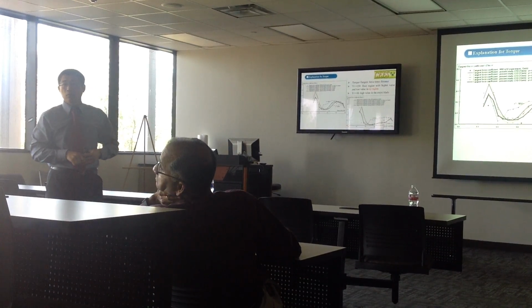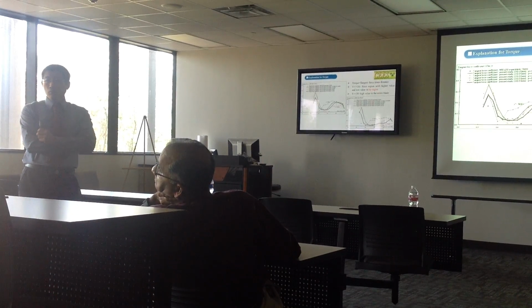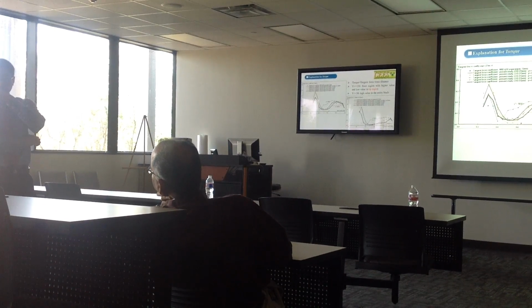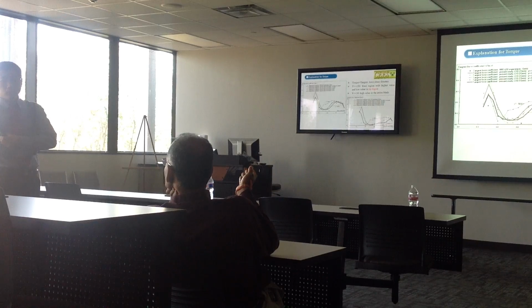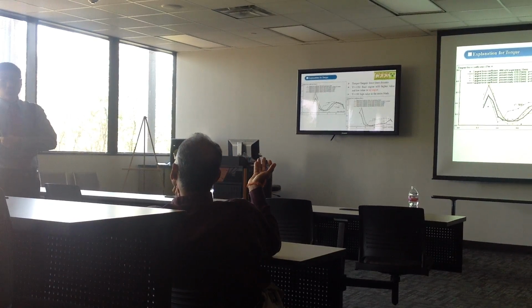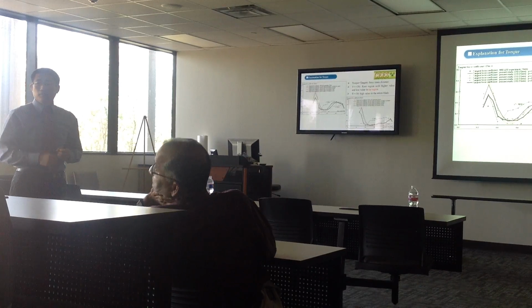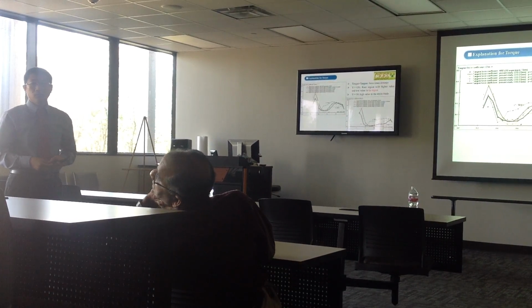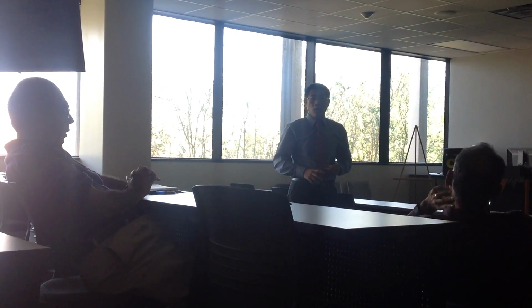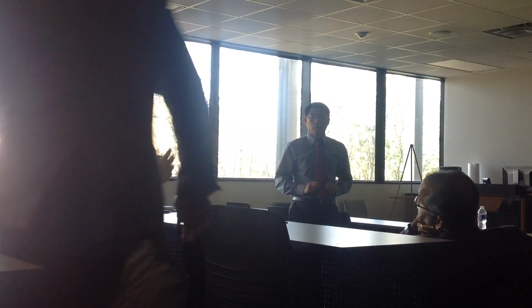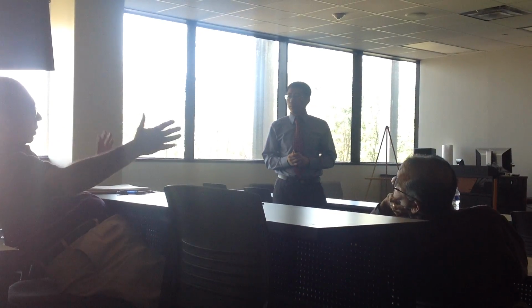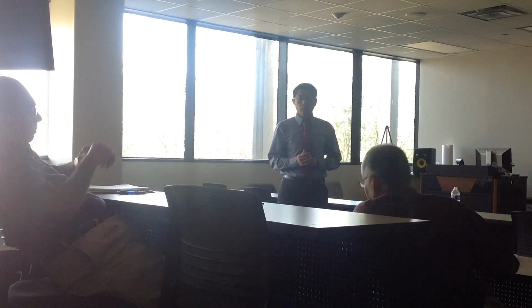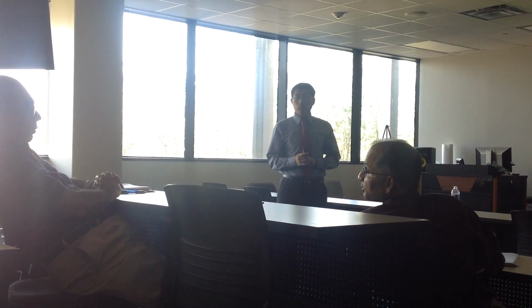See, 4 times the diameter. If I reduce that to, let's say, 2 times, will that change? I know it would reduce the simulation time, but will that lower the accuracy? Generally, if you go below that, you will deviate farther from the ideal. A normal practice is about 5 times, and on the downstream a total of 10 times the diameter. But you can increase the grid size there, right? The mesh size, when you go farther.